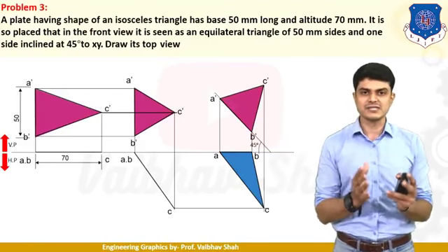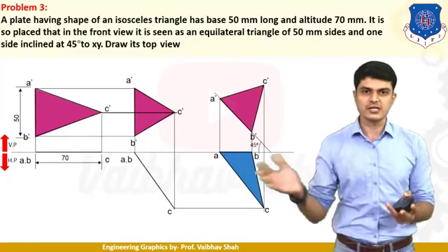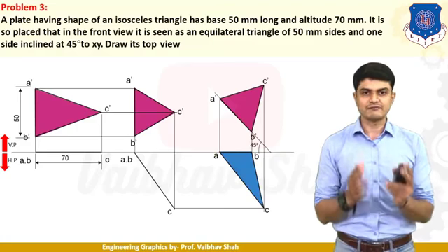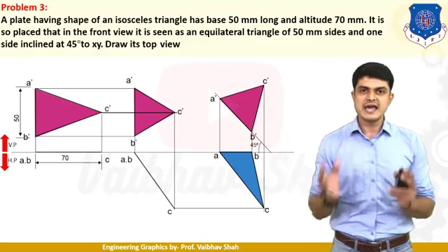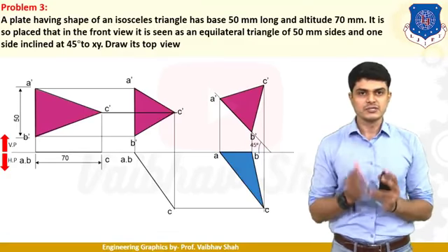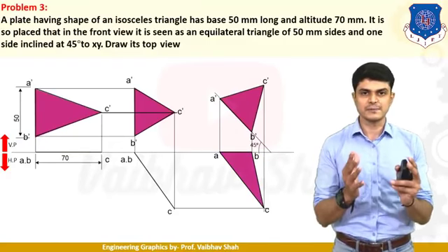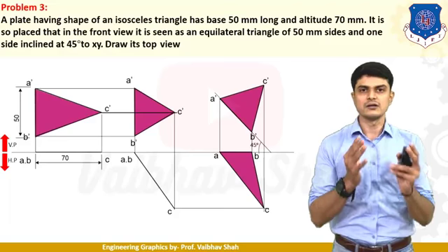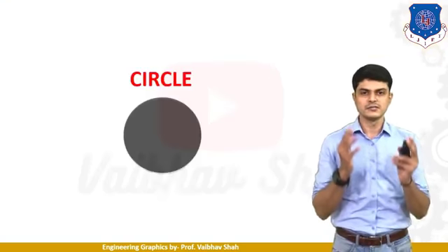And after getting these objects, it is simple. You need to draw a vertical line from this object and a horizontal line from your previous object. After that, identify the points of intersection as A, B and C. And after getting these points, you need to join these points in alphabetical order. So let us join these points in order to get this triangle generated. So this is nothing but your top view in the third stage. Very easy. So now let us move to another element.